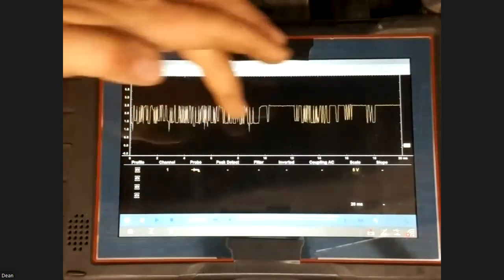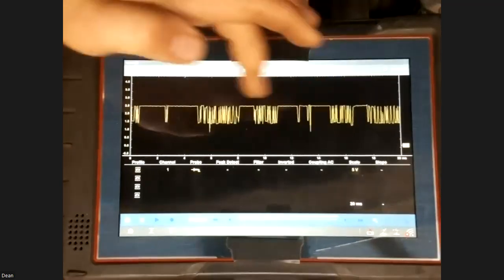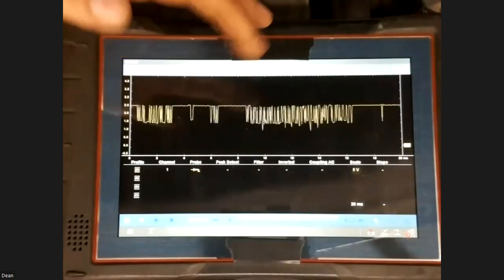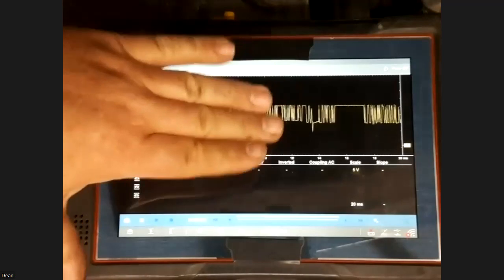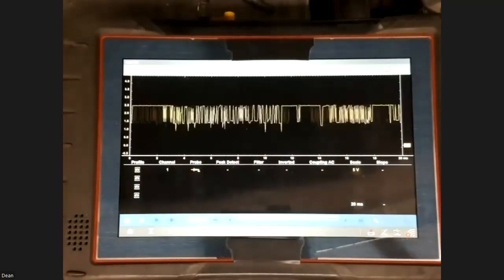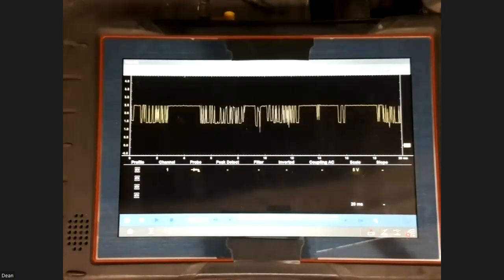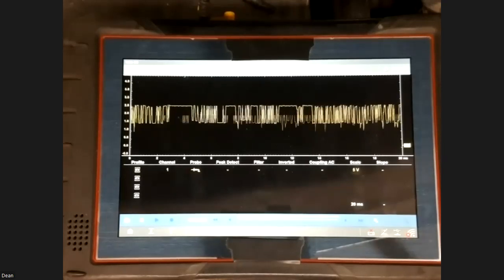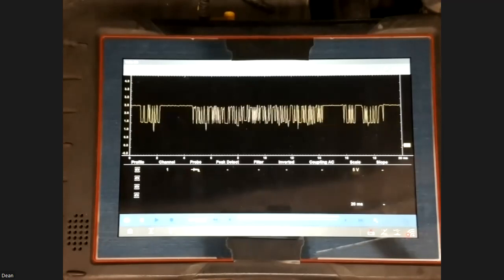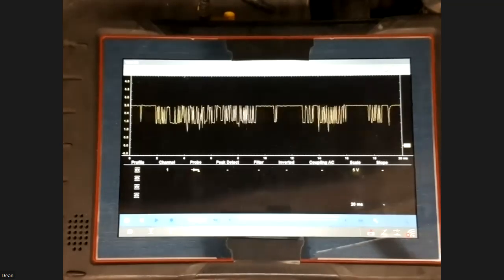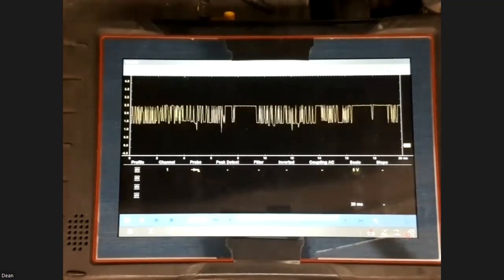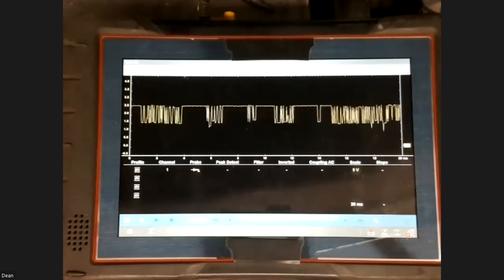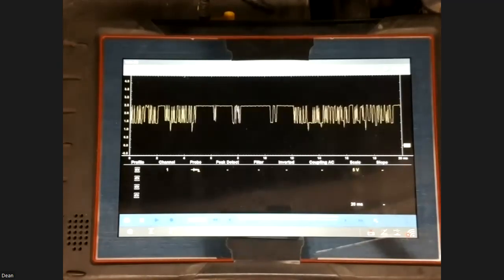See these communication packets? If you had a CAN high, it would look exactly the same. It would be a mirror image of the CAN low. CAN low is going to run from a little bit lower than 1 volt up to 2.5 volts, and then CAN high is going to run from 2.5 to 3.5. So that's kind of the system. I'm not going to get into that. That's another training in itself, and I'm not going to get myself in trouble.